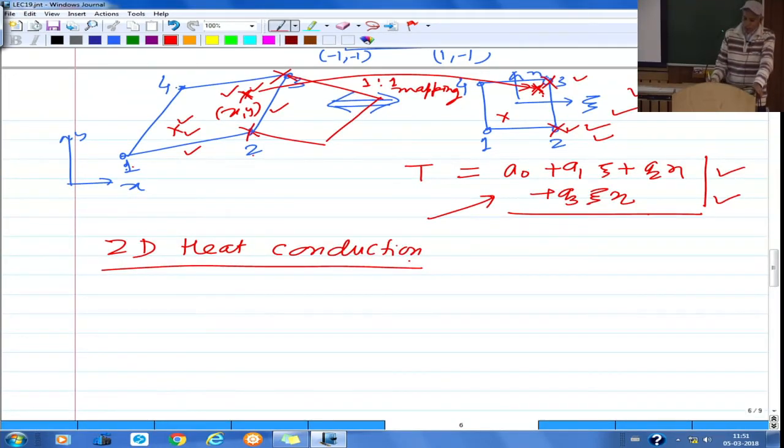Yeah, these xi and eta are referred to as natural coordinates, varying from -1 to +1. No, we always leave the interpolation in this form itself. But we have, in addition to this, the relationship between x, y, xi and eta also. But the transformation is possible. Yeah, it is possible.